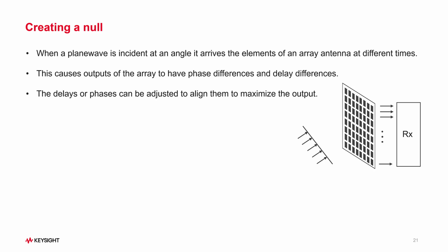We can adjust the phases in the receiver, or alternately the delays, to maximize the signal from the receiver. What we are effectively doing is all these vectors coming into the receiver, we are aligning them so that they vectorially add advantageously. This is what we call beamforming in phased arrays. So it will increase the gain as compared to a single antenna, single element. These multiple elements together will give larger gain.